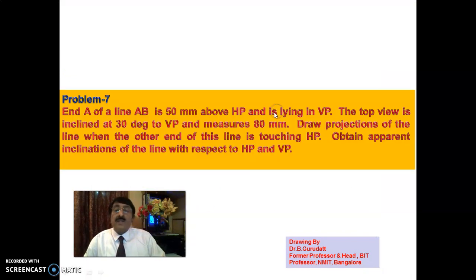Now you see another problem. The end A of the line AB is 50 mm above HP and is lying in VP. That means the end A of the line AB is 50 mm above HP and is lying in VP, so A should be on the XY line, with A dash 50 mm above. Anyway, it's not a parameter. Whatever they say, you do.